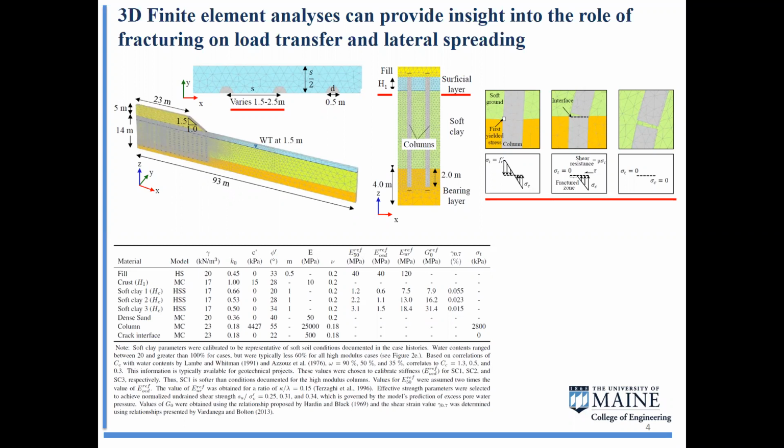And to simulate column cracking and the loss of tensile resistance, we adopted a discrete crack method whereby we introduced interface elements through the column at locations where cracking was predicted. And this allowed column rotation and separation for larger deformations. And though this method does neglect the energy release rate due to microcracking and fracture propagation at smaller deformations, it adequately introduces a constituent response to assess the global behavior of a CSE system on fractured elements.